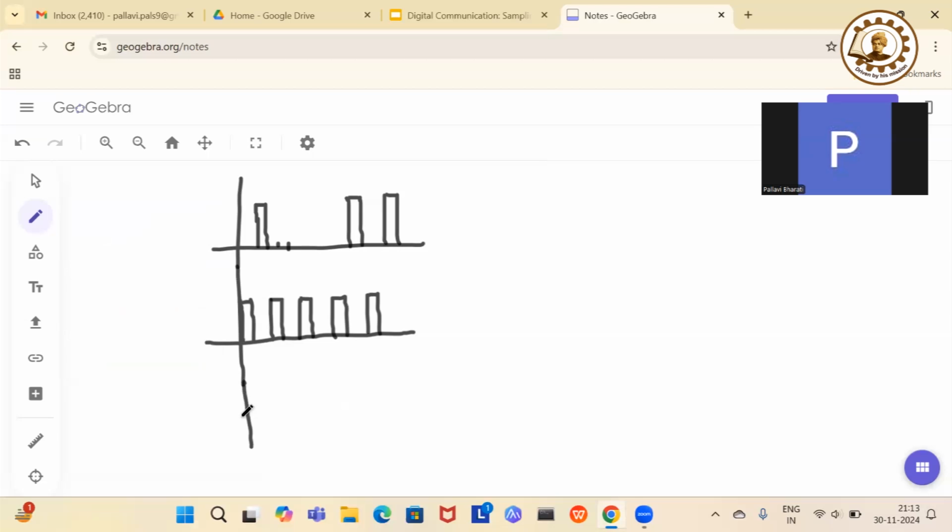So that's why we cannot keep it. Now here, this is the set pin and this is the reset. So when this is there, then it is high. Once this one is coming, at that time it will go low. Again, when this is coming, then it will become high. And it is going to remain high till this reset one is coming. Fine. It will remain high till this reset one is coming.